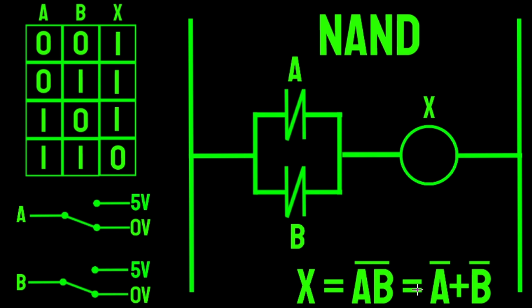but you can use something in Boolean algebra called De Morgan's theorem, where you can change the operation from AND to OR, and vice versa, if you split or merge the overbar. So in this case, we're changing the AND operation into an OR operation, and we are doing this to simplify our ladder logic. And that's De Morgan's theorem.